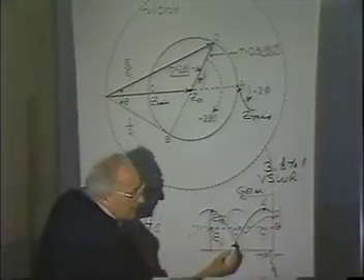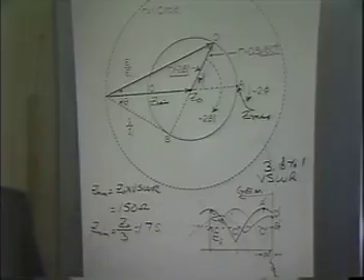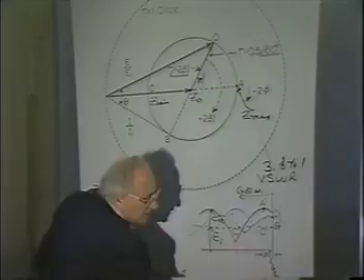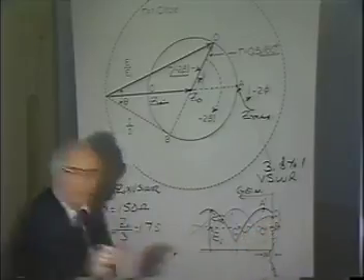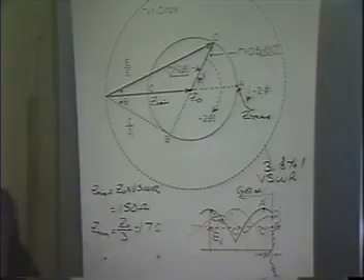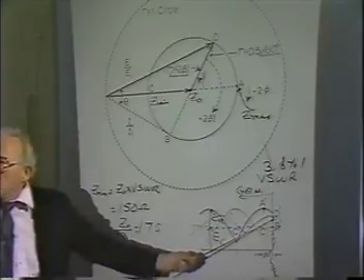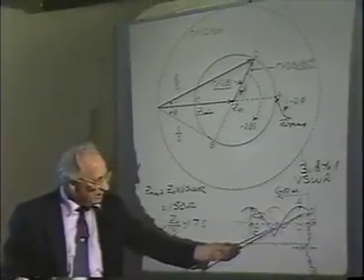Notice what has happened. The minimum, instead of being here, is over here, isn't it? You see, I no longer am terminating this with an inductance and resistance. I'm putting a pure resistance in here, just a pure resistance greater than Z0. So the maximum has to appear where? At the load, the reference plane for the load. That's this point here.